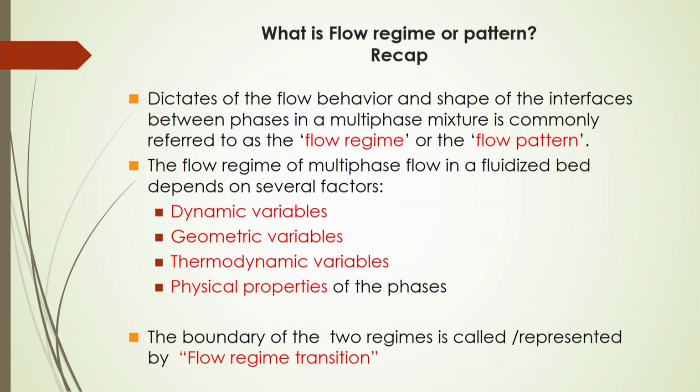Now, already we have discussed the definition of flow regime or pattern. Still we are looking back a little bit for that. So, this flow regime or pattern means the flow behavior and shape of the interfaces between phases in a multi-phase mixture, which is commonly referred to as the flow regime or flow pattern.